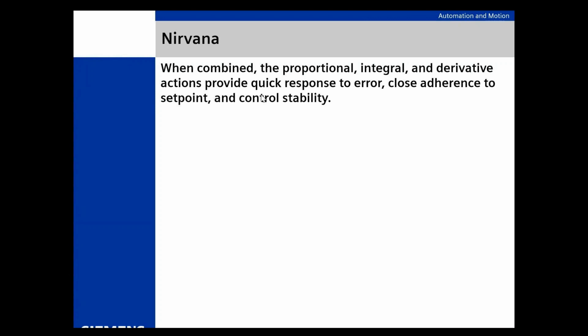The problem is what people do is when they see it overshoot, they start piling on the derivative. Well, again, now you're slowing it down. If you pile the derivative on, you're going to slow this loop down to the point that it's eventually going to either drag where you're basically out of control range, or it's going to start overshooting again because it puts the brakes on so hard, the proportional starts adding more control signal. It's going to be unstable there.